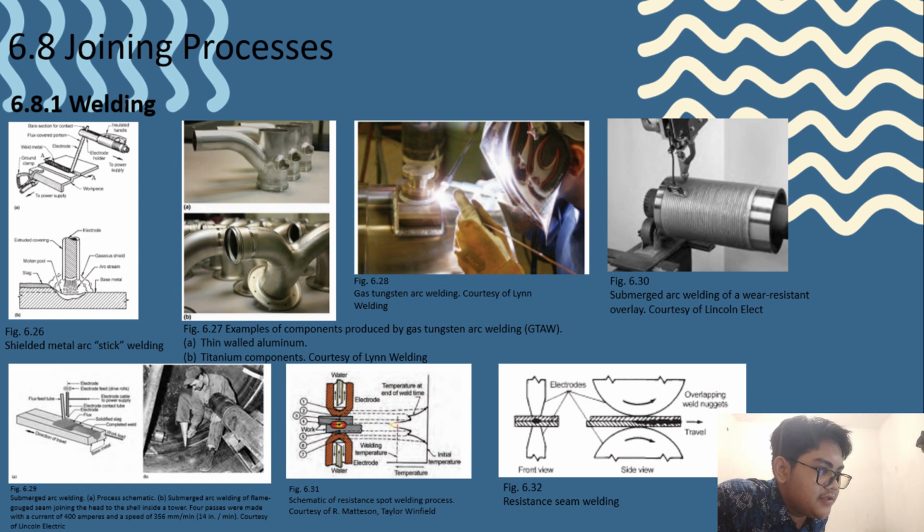Although filler metal is often used, the electrode, weld pool, arc, and heat affected zone are protected from atmospheric contamination by a gaseous shield provided by a stream of gas that is usually inert, or by a mixture of gases. The GTAW process is well suited for welding thin sections, as we can see in Figure 6.27, and foil of all weldable metals because it can be controlled at very low amperage.